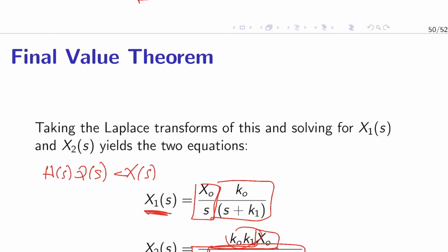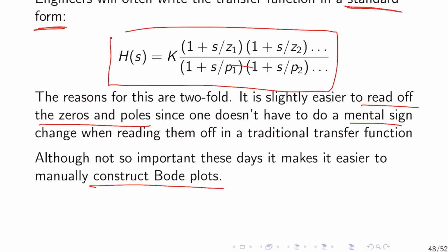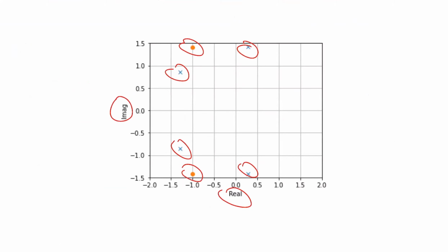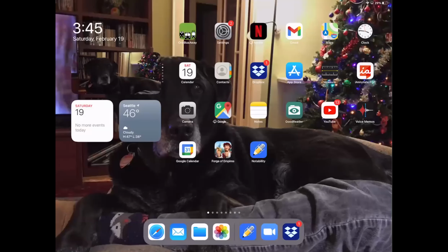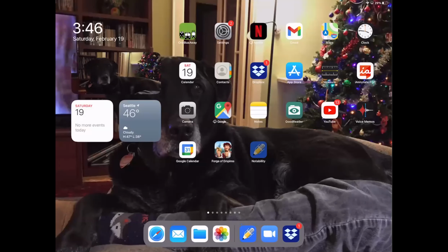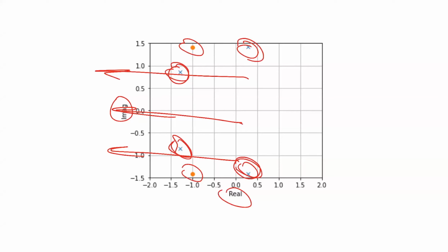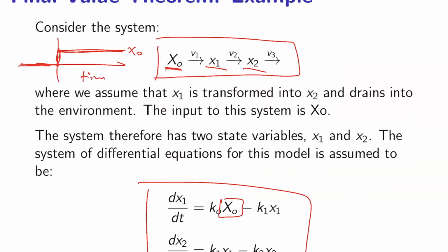We'll come back to this again, but it means also that if all the poles are in the negative, or left, half-plane, the system is stable. If you have any in the positive half-plane, you know the system is unstable. We'll come back to that another time, but I just want to mention that.